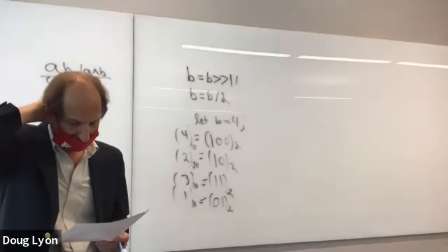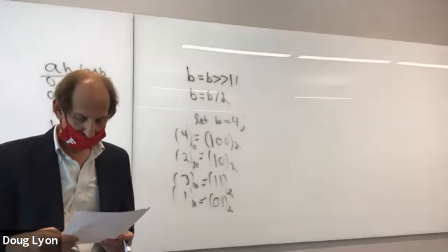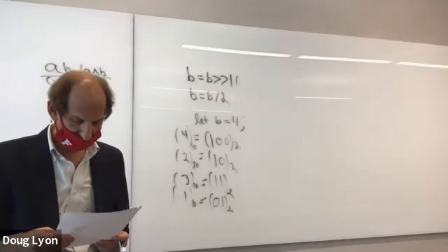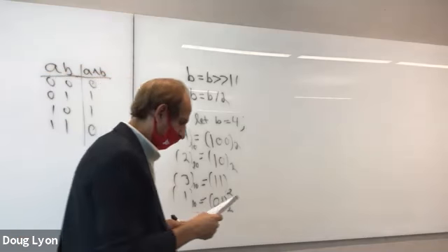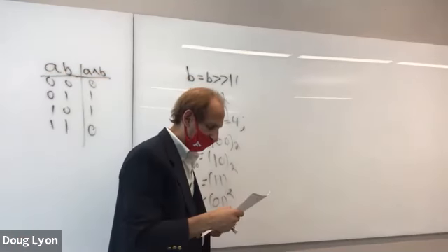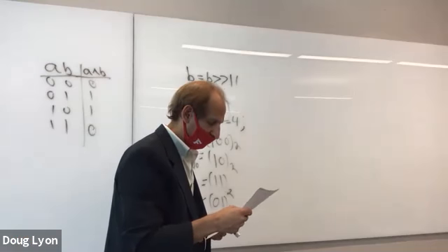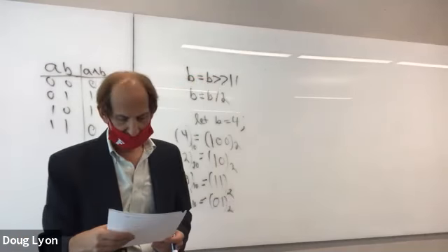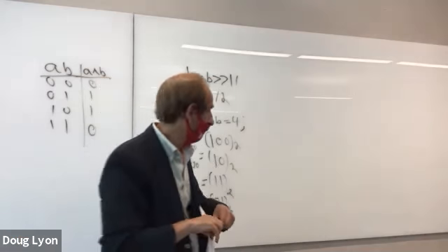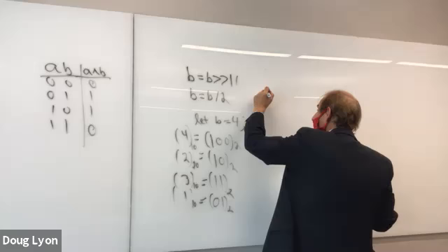Where did I get that now? I think if you do the math, it's supposed to be 5 over 220 because you're applying 5 volts. Yeah, I wonder if I got a typo there. So that's 5 over 220. 5 over 220 is not equal to 9 milliamps, but 2 over 220 does. Right. Shouldn't it be more like 5 minus 0.7, divided by 220? Yeah, so it's supposed to be 4.3. It should be. Oh, there's a bug. Okay, so there's a bug.